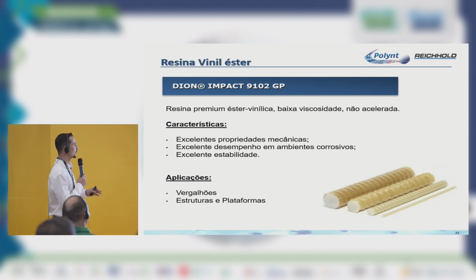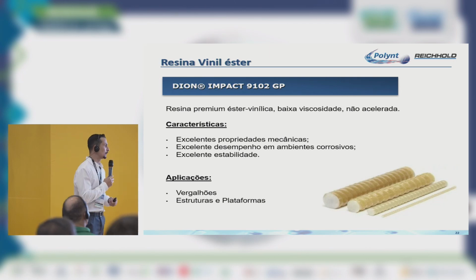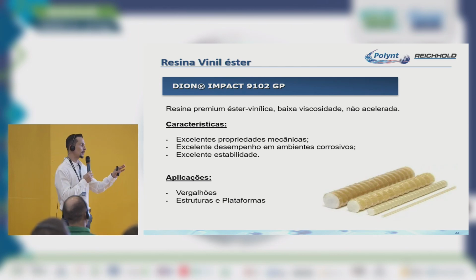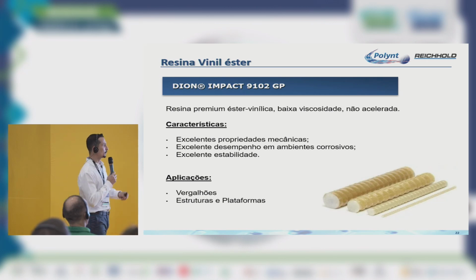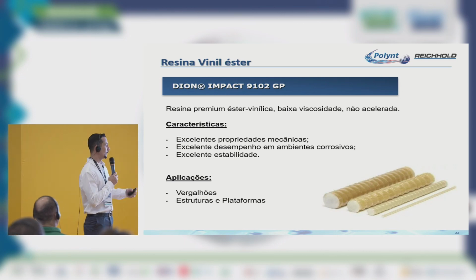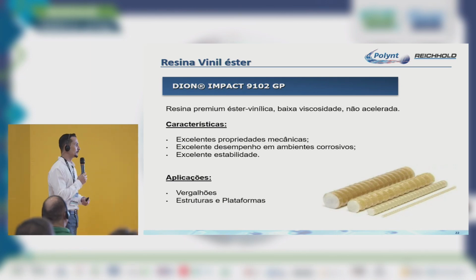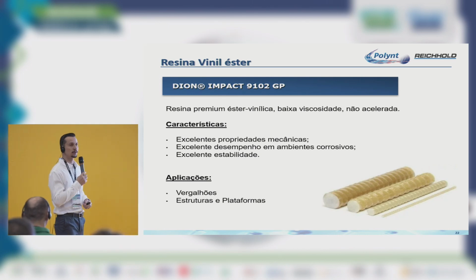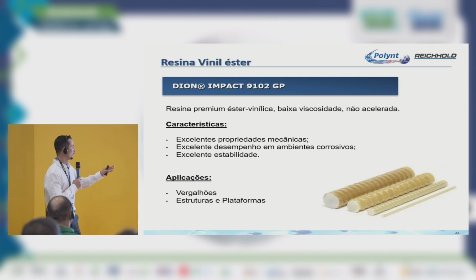Vinyl ester resin, it's a premium resin, low viscosity, non-accelerated. It's Dion 9102. Excellent mechanical properties, excellent performance in corrosive settings, excellent stability. It has elongation, it's stretchable. For example, working in the setting of hydrochloric or sulfuric acids, excellent stability. Its shelf life is 12 months.